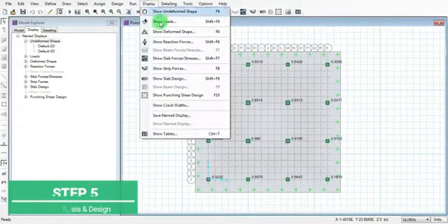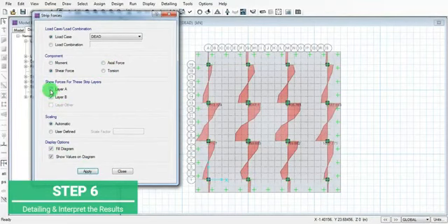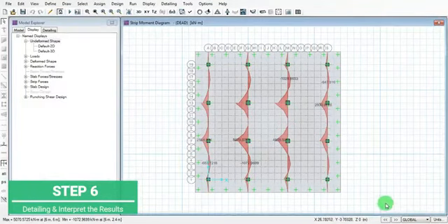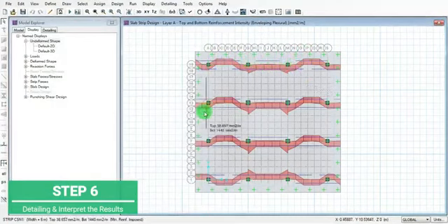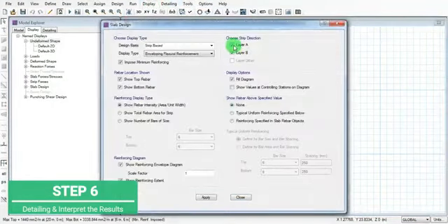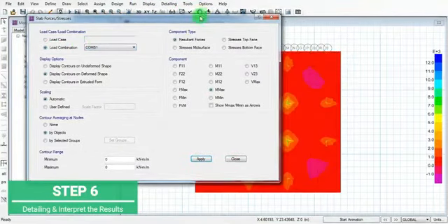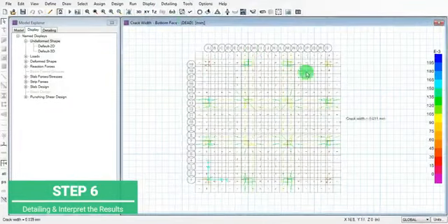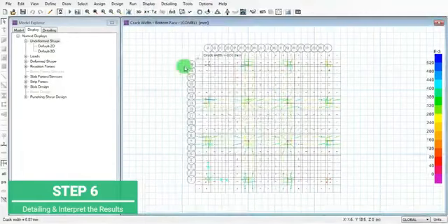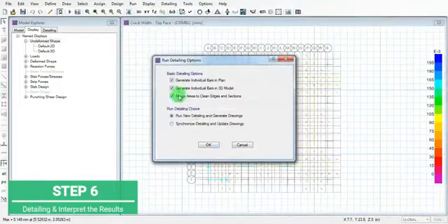Now the next part is to view in detail the different load combinations. Before that, the strip forces and all in Layer A and Layer B. Now get the required reinforcement. Now similarly in Layer B for load combination A. This is the crack width values for the slab top and slab bottom. These are minor cracks.